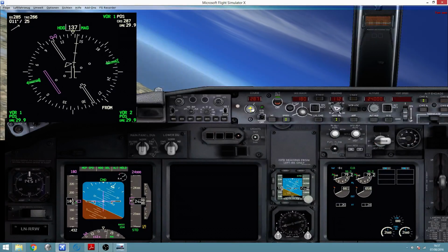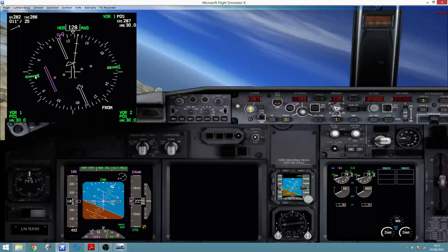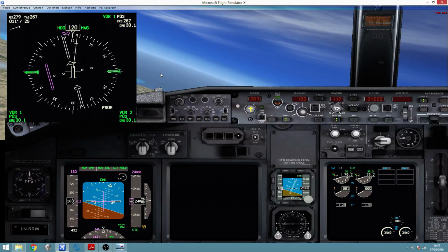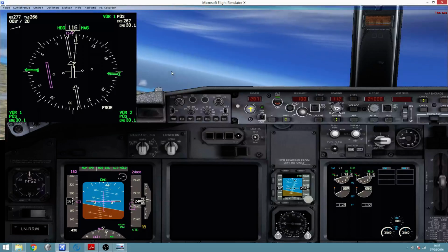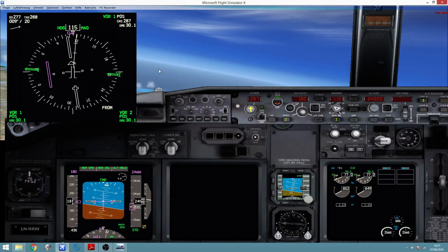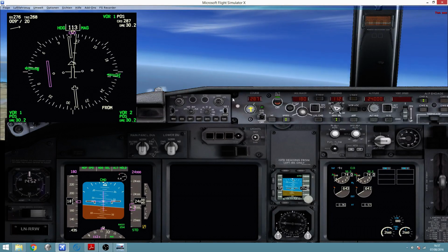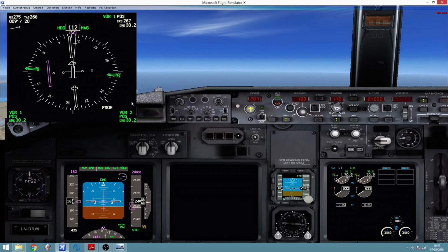And how do we navigate with respect to this VOR? Well, this arrow, as I've already said, points towards the station, but let's say I want to navigate on radial 225 of the VOR, proceeding inbound. By taking a look at this instrument, you have to be able to know your position, to be able to draw on a map your position with respect to the VOR.